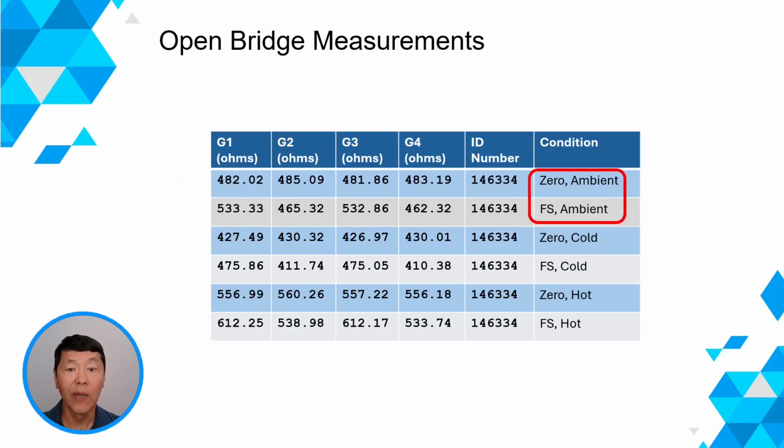But before we do that, I'd like to go through the data the Temp Comp calculator expects as input. In a previous video, I mentioned that the minimum amount of data was 4 gauge values for 2 load conditions and 2 temperatures. As you see here, we have added the requirement that the gauge resistances at ambient at 2 load conditions be applied. We recommend that the gauge data be measured at ambient to verify their function before a lot of time is spent temperature conditioning the sensor. We believe this is just good practice.